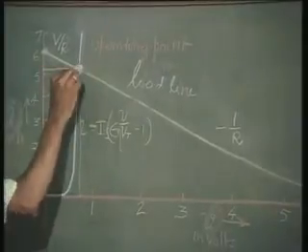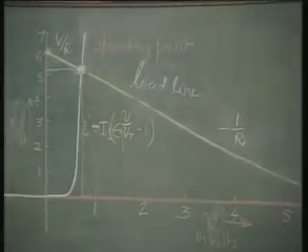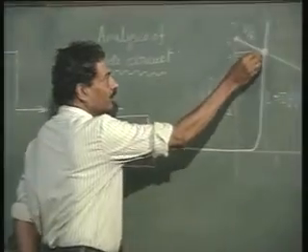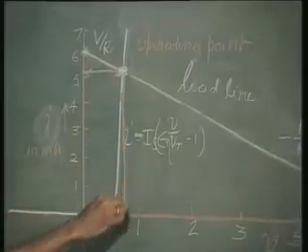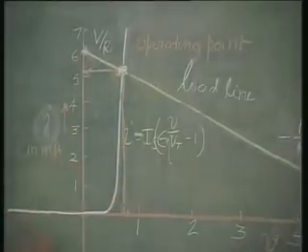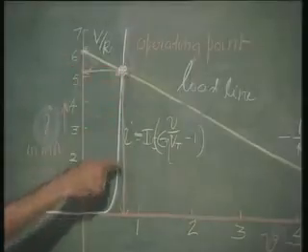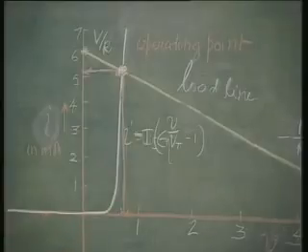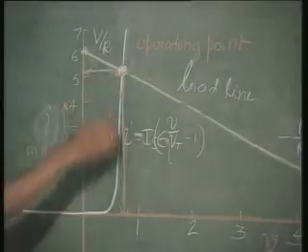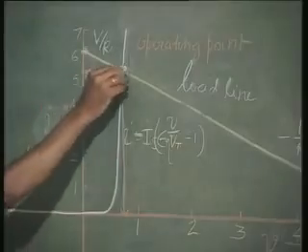So this is the operating point where there is a certain current flow through the diode that is given by this and a certain voltage across the diode. This is about 5.4 milliamperes approximately, and this is about 0.55 or so. Right. So this is the situation that we have already evaluated earlier.